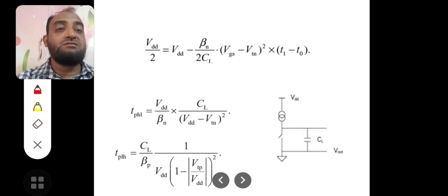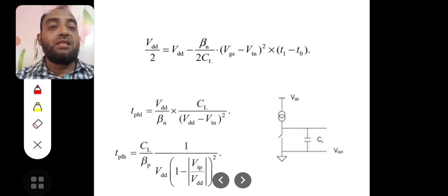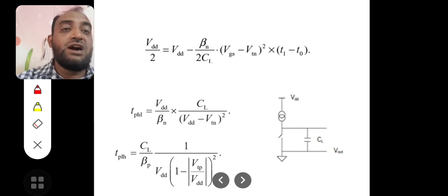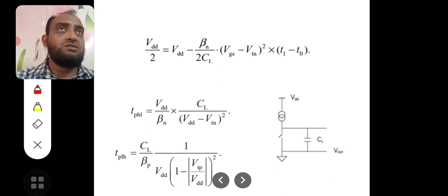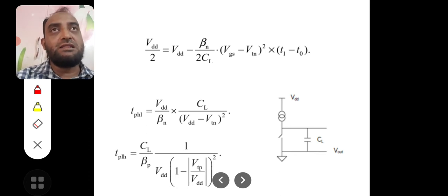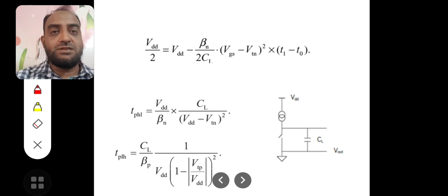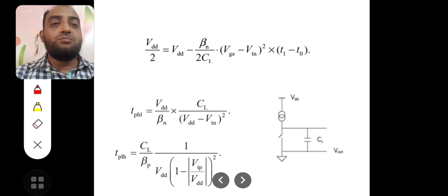By substituting the dimensional values of the pull-up device and pull-down device, the delay time is the RC time delay. We already know the value of the resistance R offered by the device, and we know the capacitance CL. We have just discussed this in the previous slide, and already derived it in the previous section.